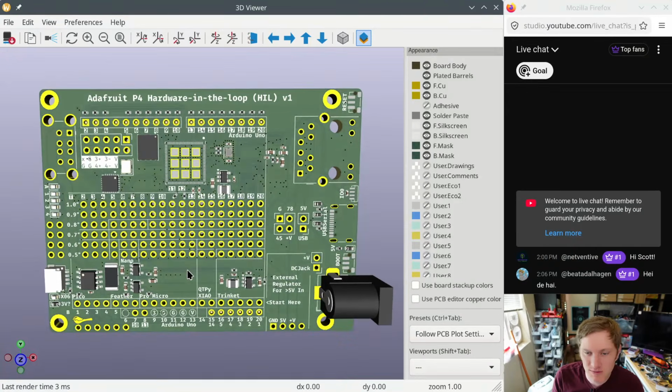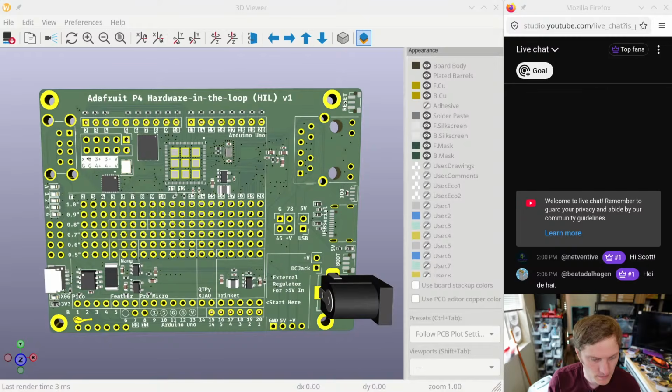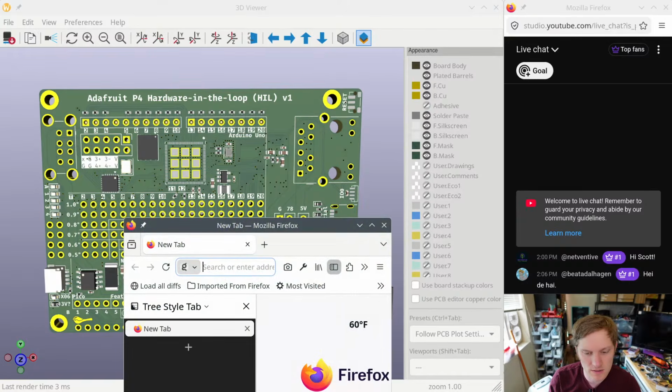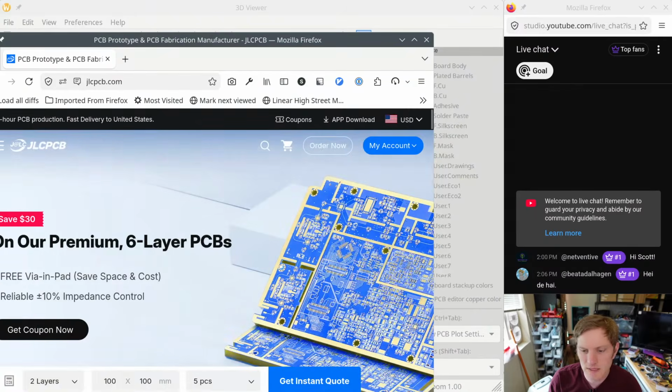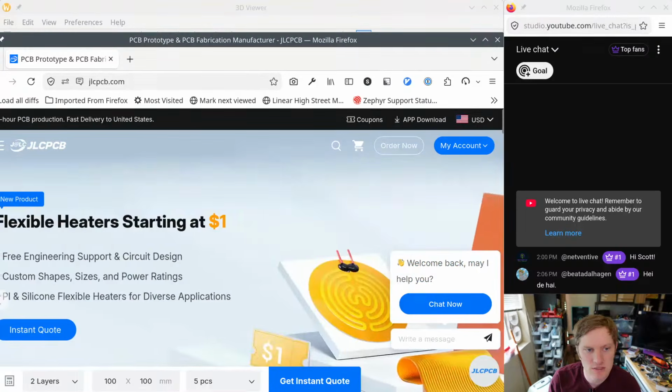Depending on how much you want to spend, you could order it off JLC after I've done it. All of the files for ordering from JLC I do just commit. But a lot of the cost for getting 5 is setup time. One of the unfortunate things is that they have 2 levels of assembly, standard and express, or some other term. If you do the cheaper version, they have basic parts, and then it doesn't cost you money to put the feeders in the machines because they always have the basic parts in the machines.